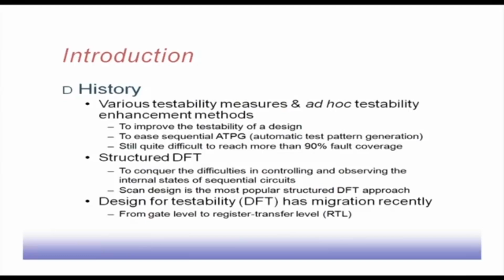So, that makes it more difficult. Putting some value into the internal flip flops becomes difficult. You want to observe and control the internal states, and that becomes difficult. So, what came up is the scan design. Scan design is the most popular structured DFT approach, because it puts all the flip flops onto a shift register, so that we can shift in the test patterns and shift out the responses from them.